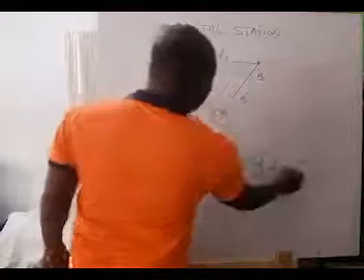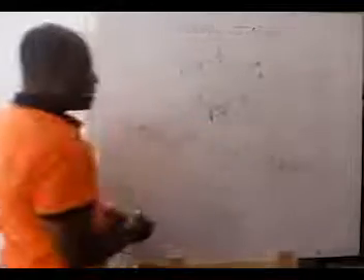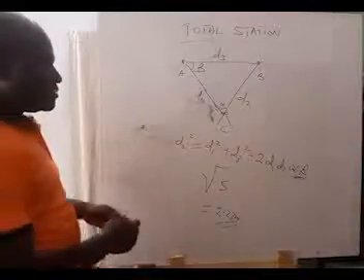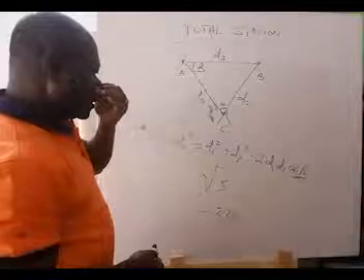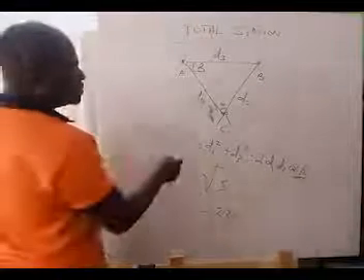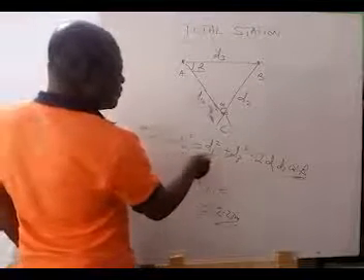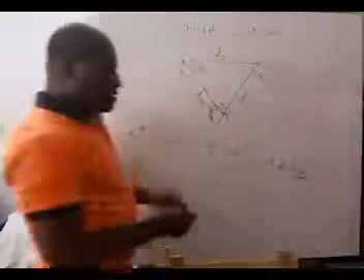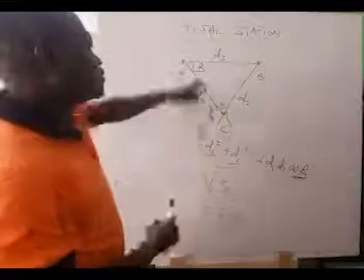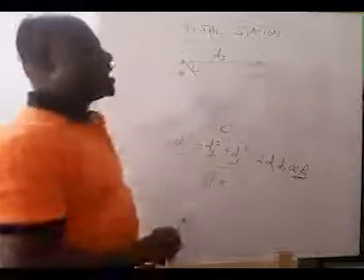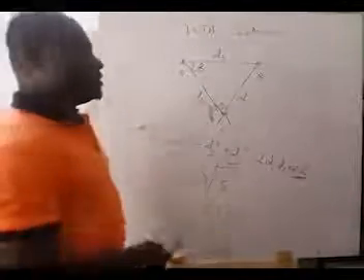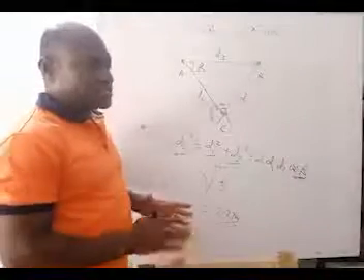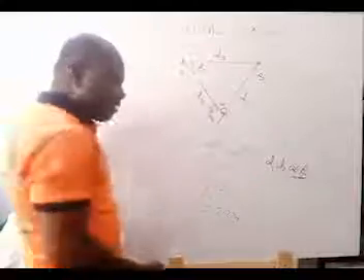It's beta we want, cos beta. You use this formula, then it makes cos beta the subject, then it's able to get beta. Because it knows D2, it knows D1, it knows D3, so it's able to get cos beta. As soon as it gets beta, it adds it to this bearing, it has the bearing for AC, and that's all. It's good to go. It's able to calculate the coordinates, orient the total station, and then calculate all the coordinates that it needs.